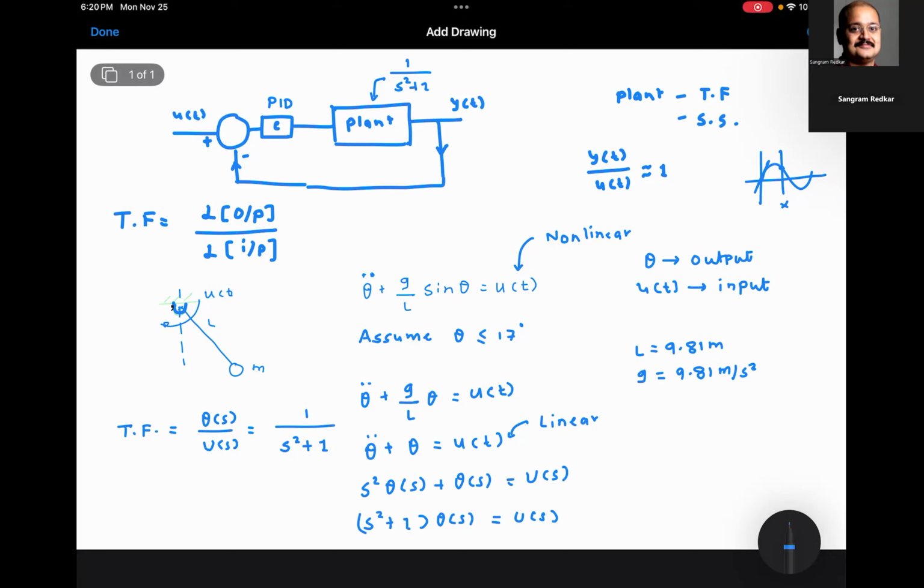So as long as possible, try to use linear control even for a nonlinear plant. And if the linear control is not working, try to use gain scheduling. If gain scheduling is not working, then you can go with feedback linearization or some other elegant backstepping techniques to design the controller. But the strategy would be to start with a linear control, even though the plant is nonlinear. Everyone understood this?